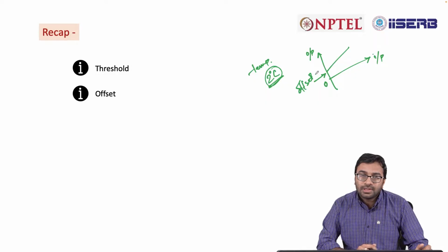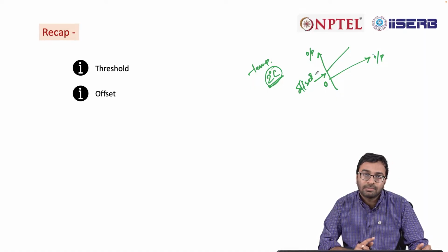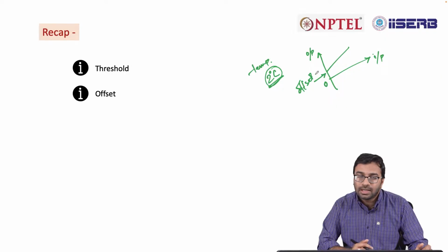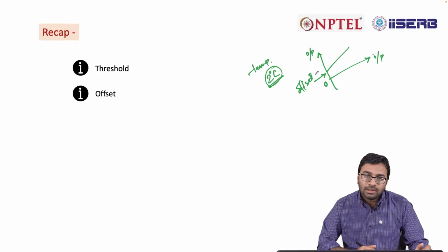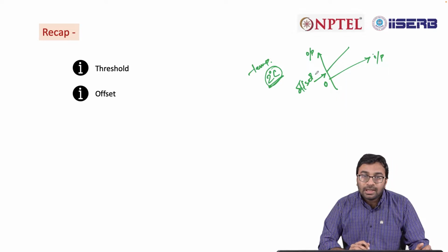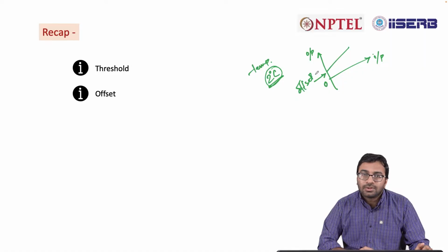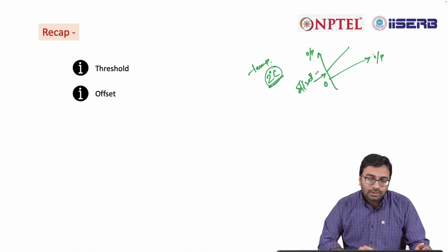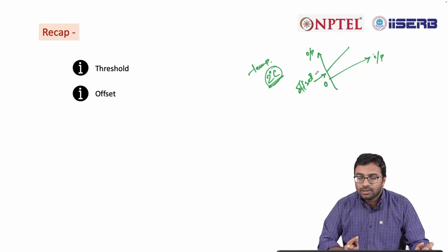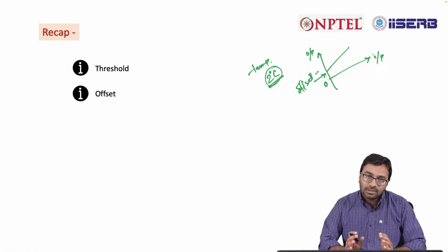Apart from that, offset may also come into your sensor system because of linearization, as we have seen in the previous lecture. Once you linearize the calibration curve, due to that linearization process, you may end up getting an offset in that. But again, you can work with it, but you have to take care of that offset properly, otherwise things may not work as you wish. Secondly, it's not a property completely associated with the sensor. This also can be associated with the system. So offset can come in your entire sensor system because of the circuits that are there in the system.